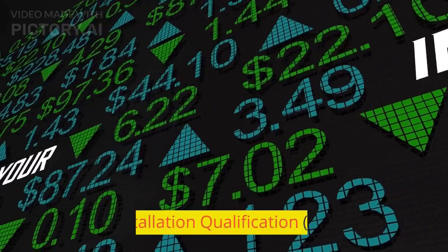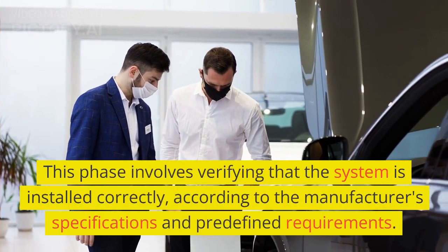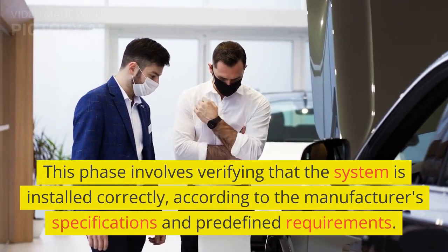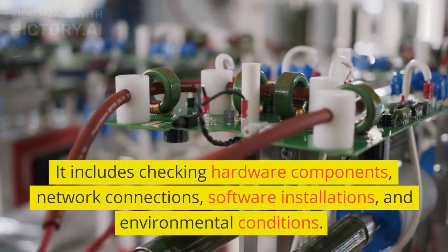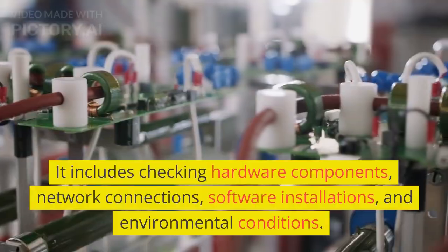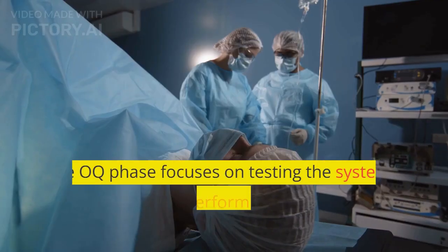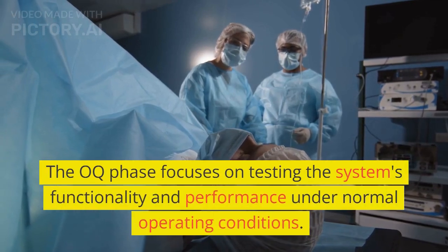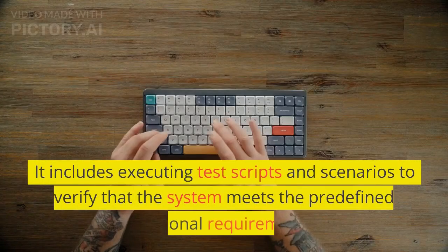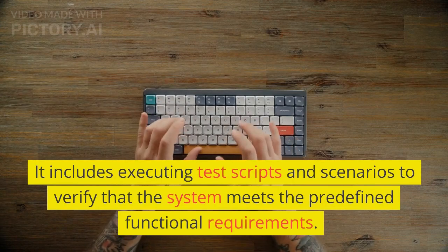5. Installation Qualification, IQ. This phase involves verifying that the system is installed correctly, according to the manufacturer's specifications and predefined requirements. It includes checking hardware components, network connections, software installations, and environmental conditions. 6. Operational Qualification, OQ. The OQ phase focuses on testing the system's functionality and performance under normal operating conditions. It includes executing test scripts and scenarios to verify that the system meets the predefined functional requirements.